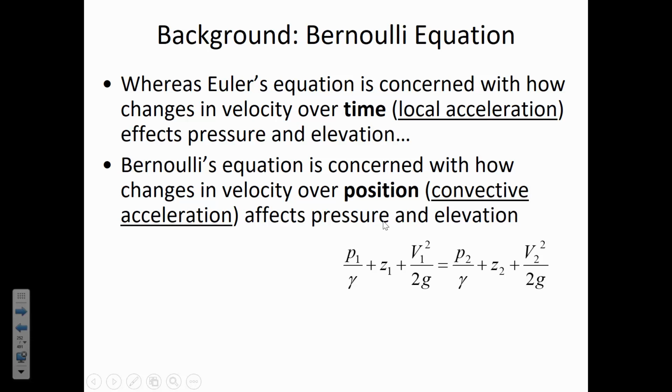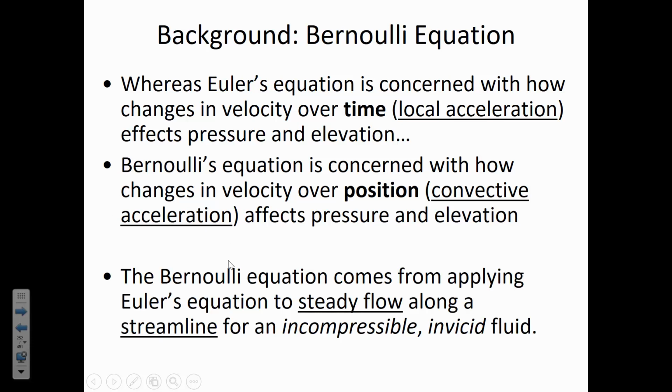And so an inviscid fluid is going to be one that experiences less or no energy loss due to pipe friction. And so the more viscosity you've got in the fluid, or the faster the velocity, just in any way, anything that contributes to energy loss is going to make Bernoulli's equation less accurate as a model.